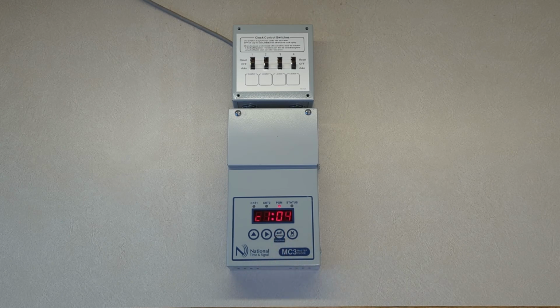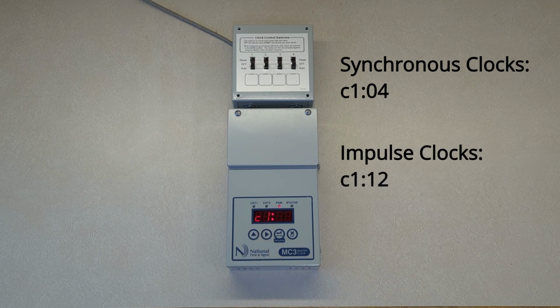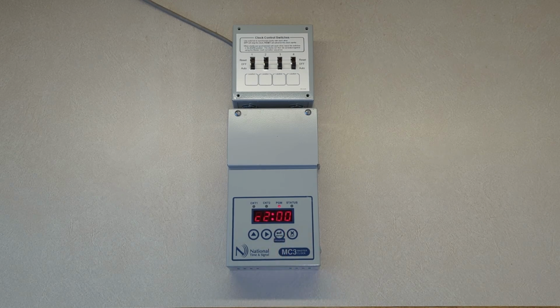Now you can choose the circuit type for circuit 1. Use the up arrow to scroll through the choices. For synchronous clocks, set the circuit type to 4. For impulse clocks, set the circuit type to 12. With the correct circuit type selected, press the Enter button.